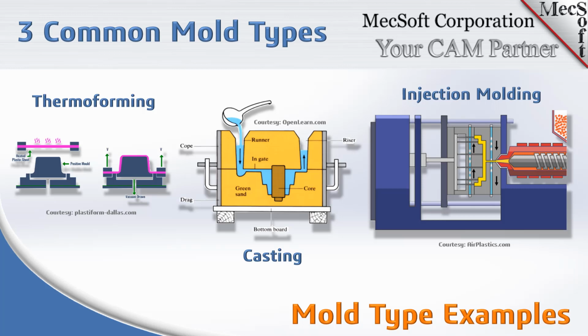Thermoforming just drapes a heated sheet of plastic over a core model. So all your machining in our product is the actual core, and you don't have to machine any cavities or anything. Typically the tolerances are relatively loose. The only thing you need to make sure is that you have the right amount of draft, because that plastic has to slip off of that core very easily.